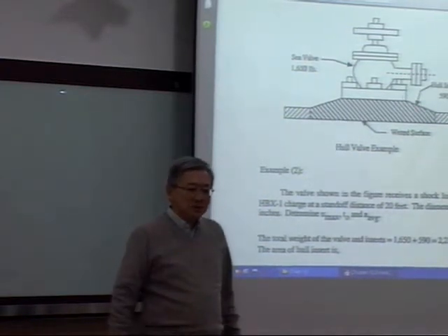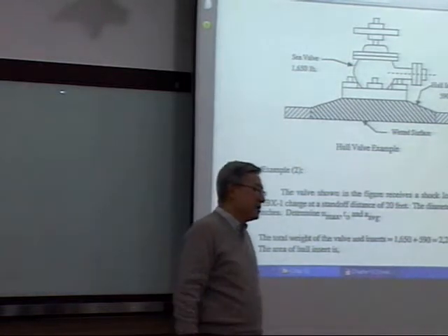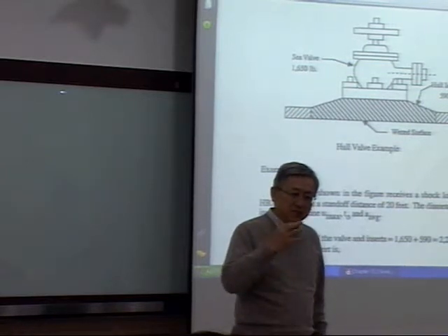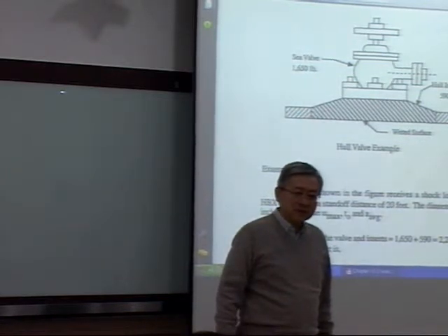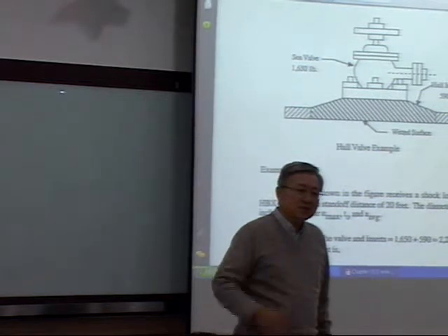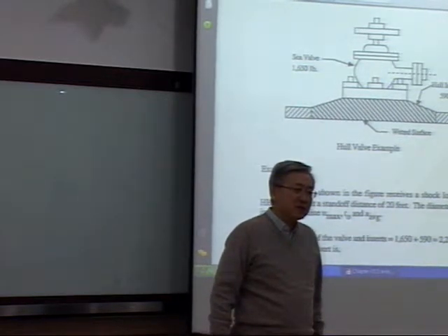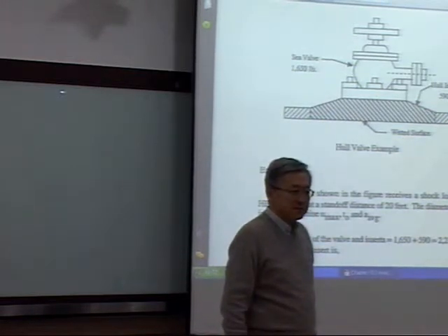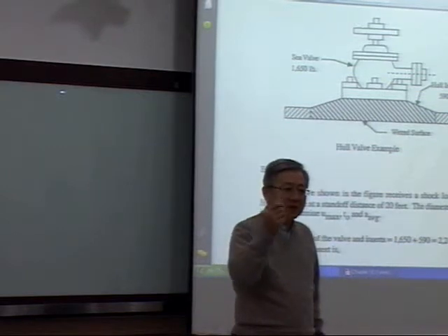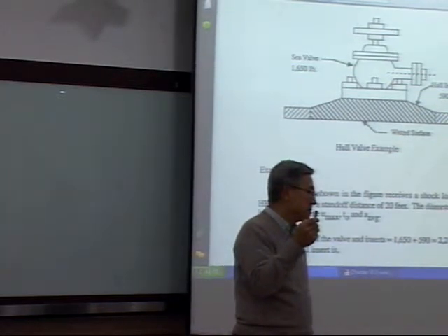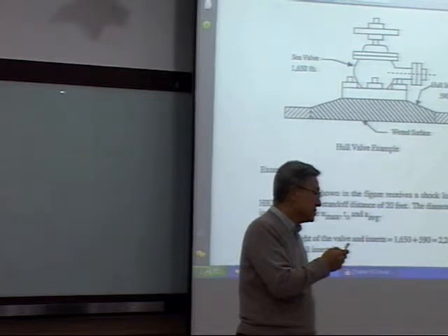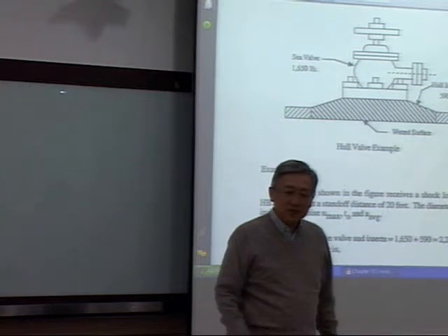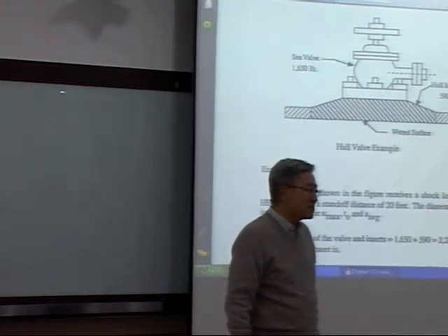So there is a DDAM approach, which is the Dynamic Design Analysis Method, which I'm going to teach you. So the shipboard equipment analysis was developed originally to do something like a 20 degrees of freedom model. One point in the model has how many degrees of freedom? Say 6. 6. 3 translational, 3 rotational degrees of freedom.